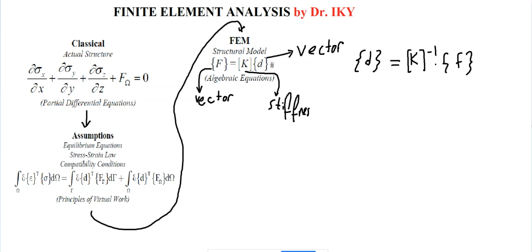And for the action, for the solid elements you need loads, for the fluids you will need body forces, and for thermal you will need heat action. Considering these, we will get a response of displacement for the solid elements, pressure or velocity response for the fluid, and temperature response for the thermal analysis.